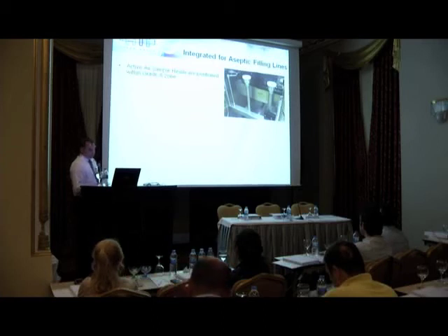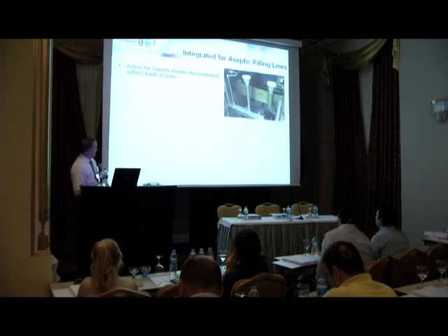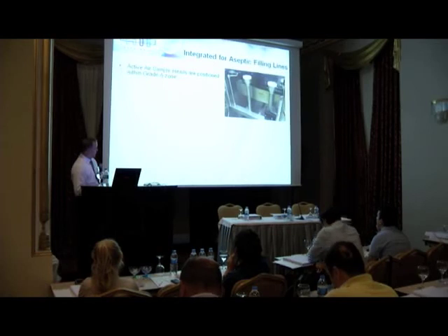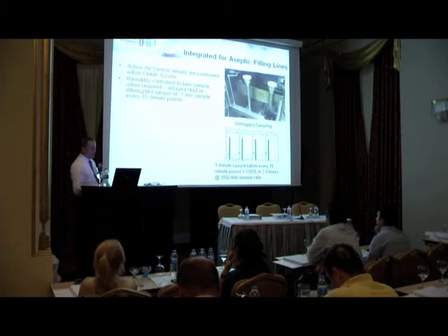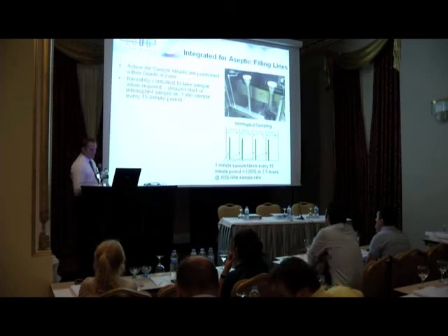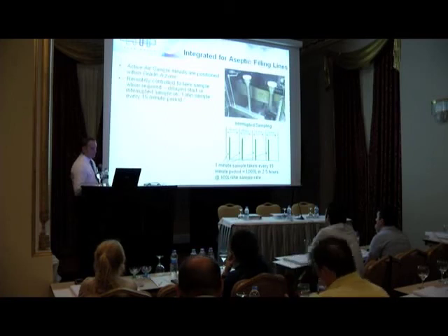So the active airheads, as briefly stated, are put into the grade A zone. Here you'll see an active airhead. There's a tube underneath which you can fill it with a cable, and that will come to the outside of your container, be it an isolator or filling machine. It's remotely controlled, and in this case we're going to use a delayed start. We're going to take a 1 minute sample every 15 minutes. And what that means is that we're going to take 1,000 litres over 2.5 hours.